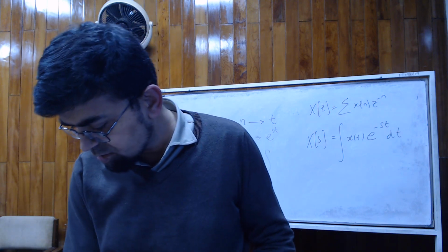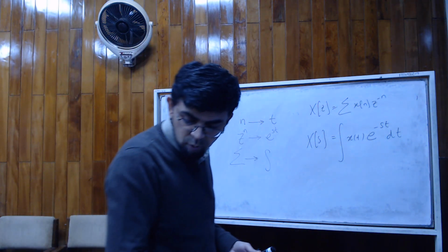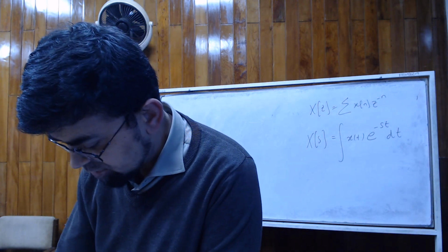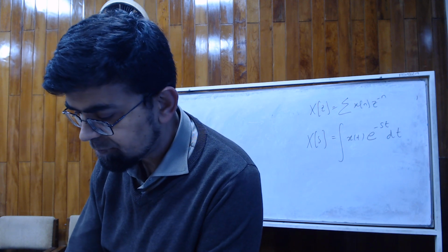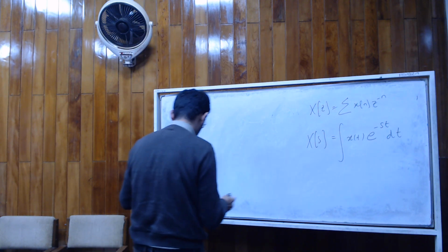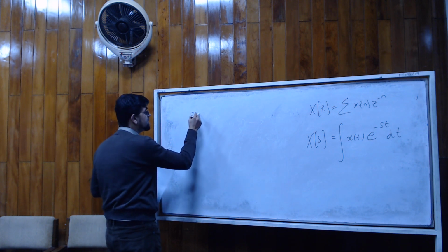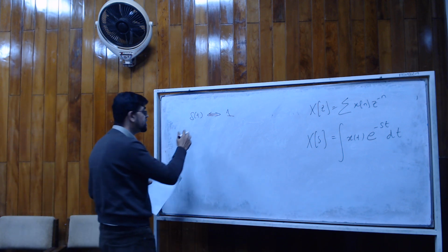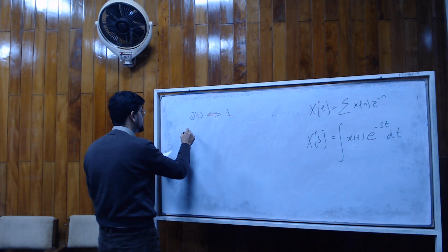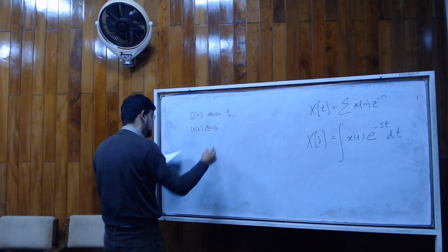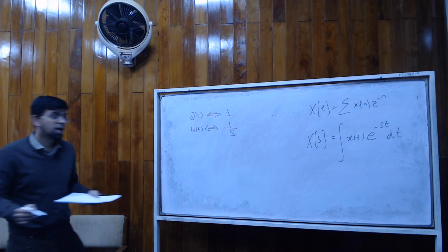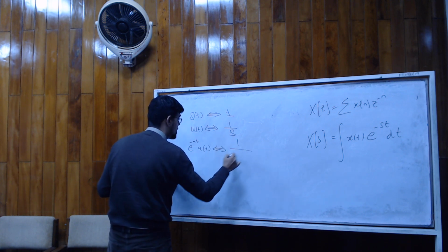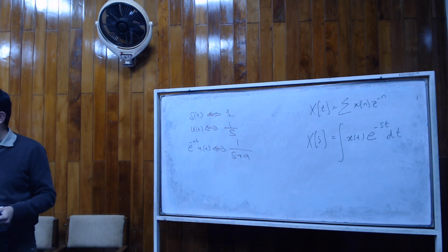Then we discussed several other aspects of this, but briefly, we found the Laplace transform of three functions, if you remember. Which functions did we take the Laplace of last time? It was the same as what we had for the z transform. Very similar. So delta t had a Laplace of unity, and then our region of convergence associated with each one. Then we had our other favorite, u(t), the unit step. What was its transform? 1 over s. And then we had e to the minus at u(t), which gave 1 over s plus a. So these are very important ones.